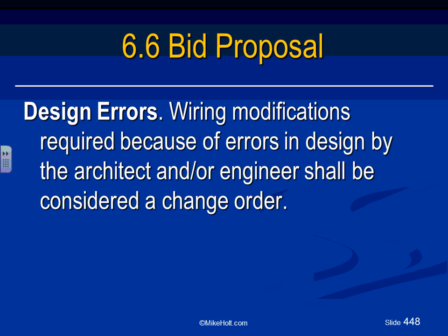Design errors. If you have a design error, you guys like to make fun of engineers, a few of you here. If the engineer screwed up with the design and you need to redesign it and send it back to the engineer, that's also a change order and has to follow the change order command. So you have to redesign it, send it to the engineer, approve it. But before you redo the project, you have to set it as a change order because somebody has to do this work, redesign and reinstall it. It might cost you more to redesign the project and reinstall it.